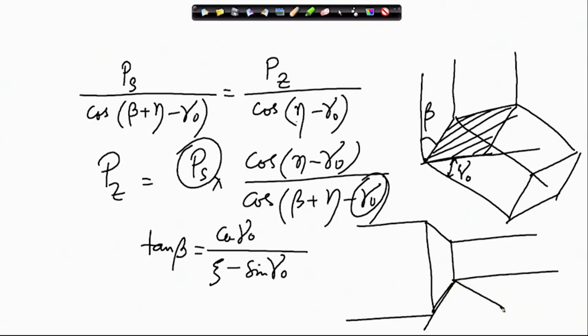if this be the tool, I hope it's visible, yes. This is the section that we are talking about. Looking from the top, on this particular view, the inclined section can be viewed. Okay, we are seeing a component of this particular section. So this distance, how much is it? This one. So we have this to be equal to t by sin phi.